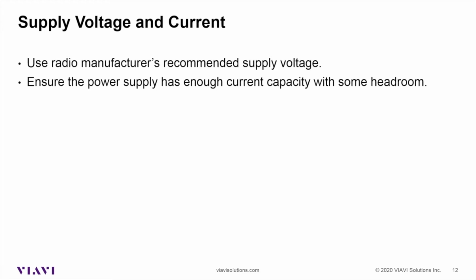So as far as the power supply goes, it's a good idea to have, and I know it costs more, a power supply with a sense line that you can monitor the voltage at the radio end of that wire harness. If you don't, at the very least, make sure you're using heavy enough wire to support that radio.